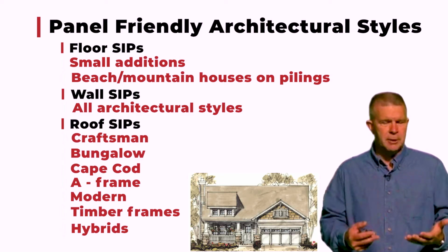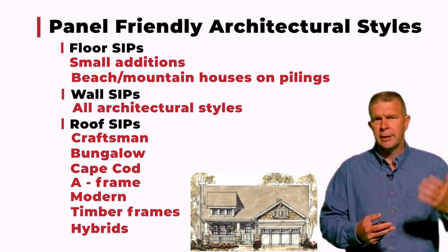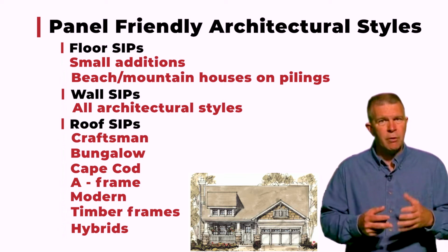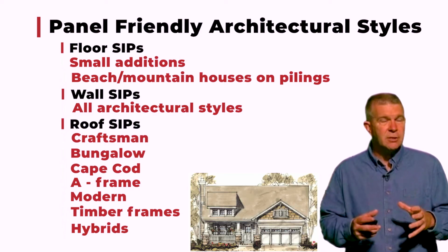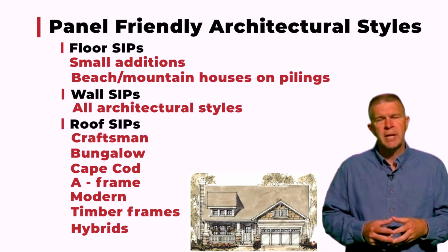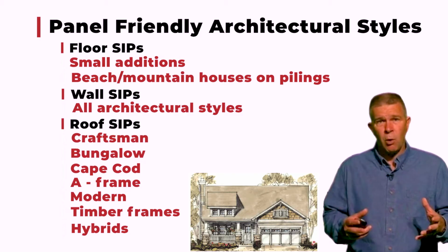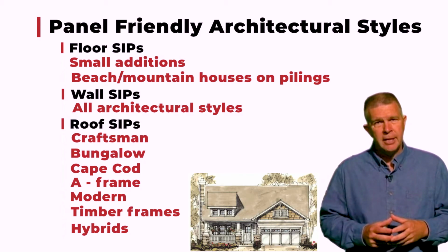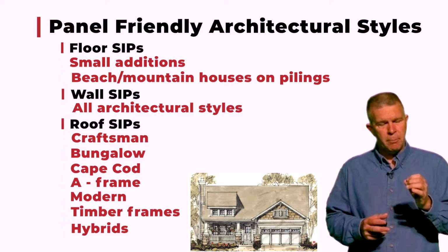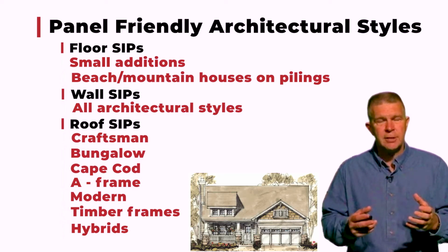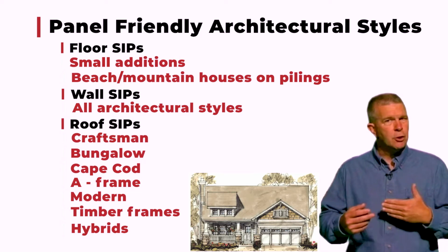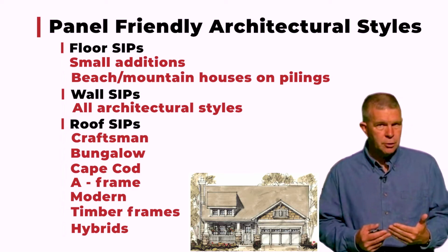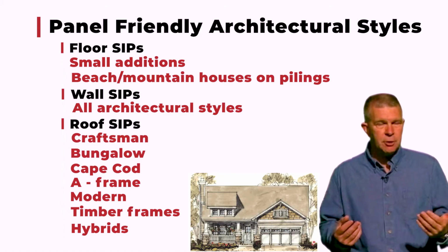So if we're building at the beach on top of pilings, or at a snow resort raised up off the ground, that's where the floor systems start to make sense, and it's a panel-friendly issue. If we talk about wall SIPs, where can wall SIPs be used? It doesn't matter what you can roll out and look at. If it's been designed by an architect and designed for sticks, SIPs will work just fine. There's no limitations when you are looking at a wall use of SIPs in any application or any design.